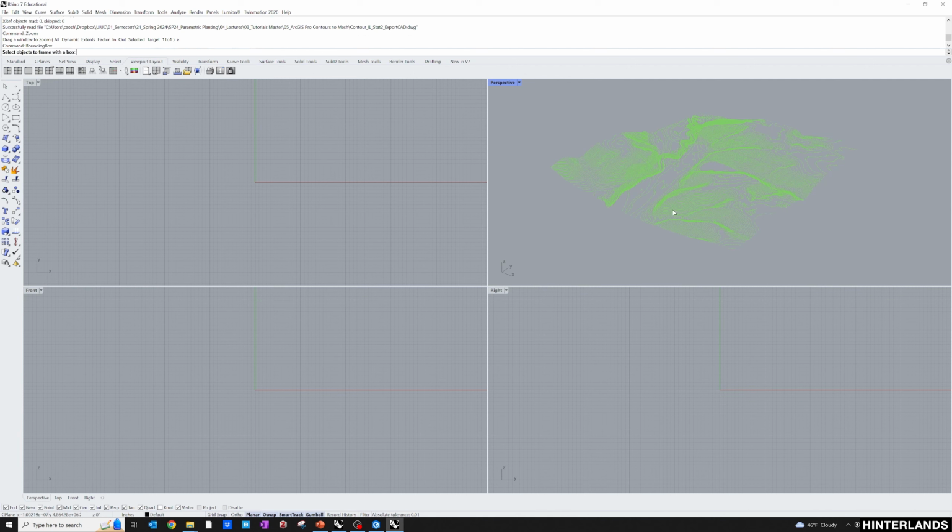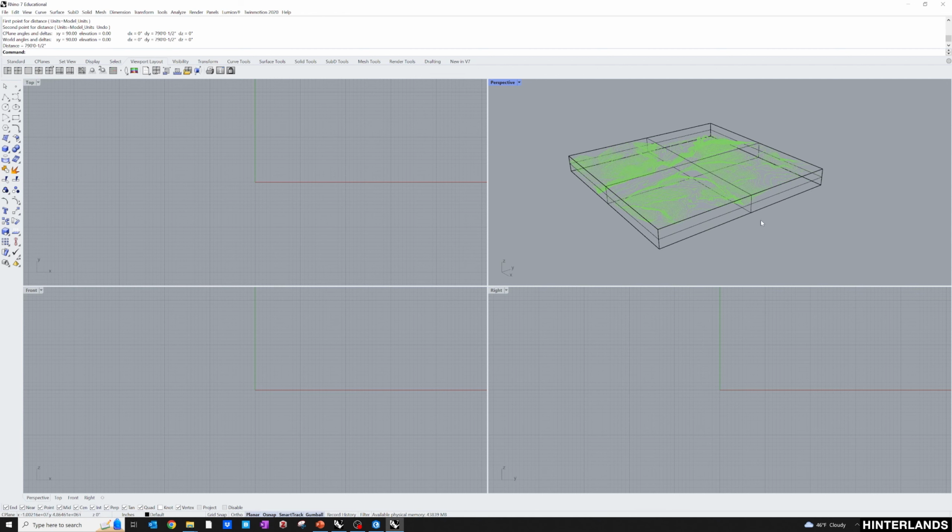And maybe while it's doing that, we can also look at it a different way. We can open the attribute table, and we can see actually the range here. So 542, let's sort ascending. 542 all the way to 617, and we can see that reflected in the labels. So that seems reasonable what we have here, but we're going to need to change the scale of this.